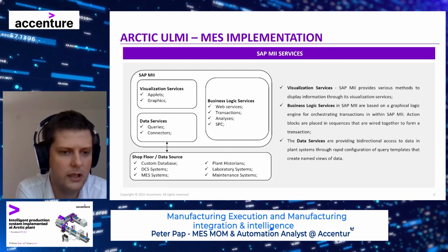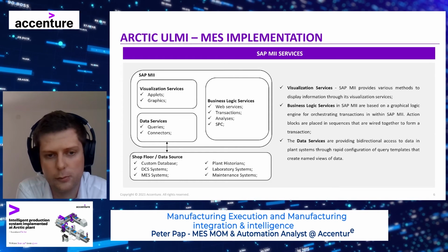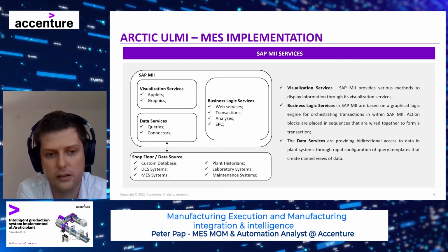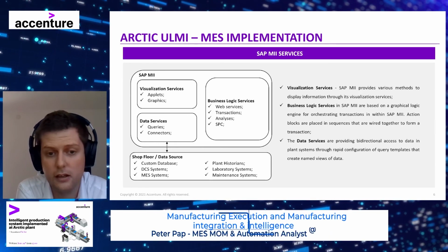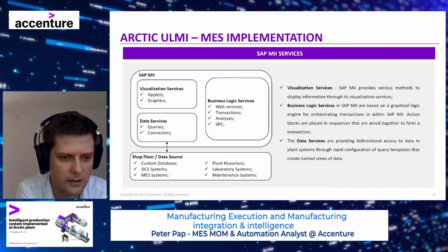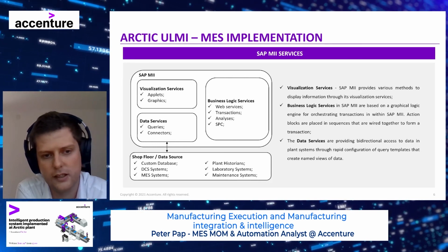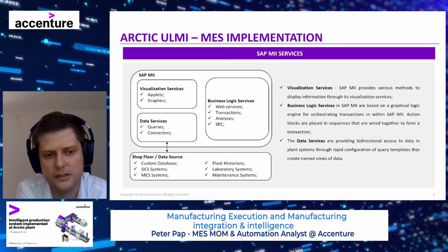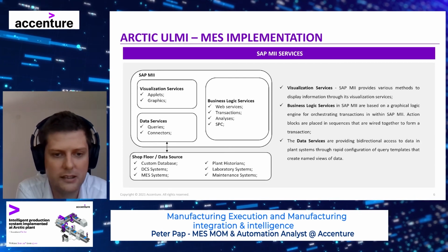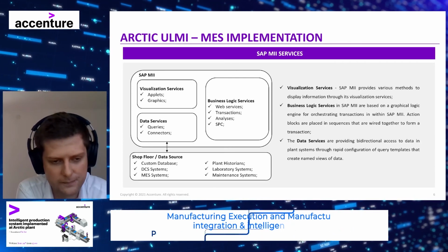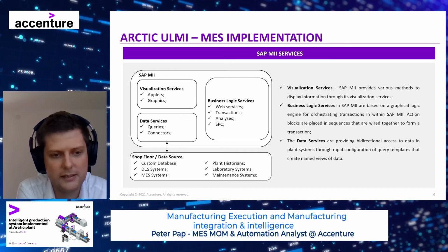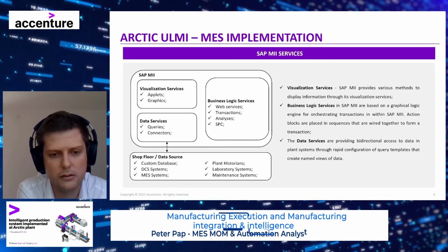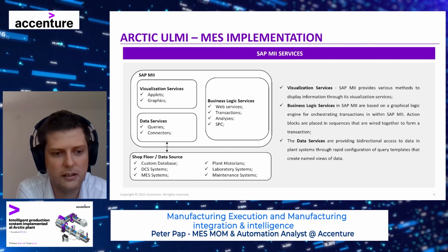For example, in MII, there is an object called SQL query template in which we can choose a data source from the previously configured SQL connection list, write the optionally parameterized SQL query, as the SQL query template object can take input properties, and then we can execute the implemented query templates standalone or integrate in a transaction logic. What is important is that SAP MII normalizes all the data, regardless of its source, into a standard XML structure.